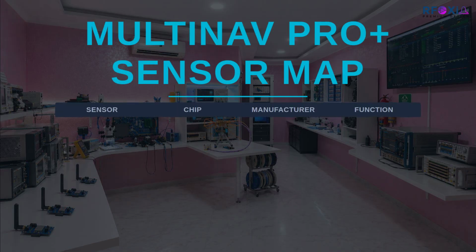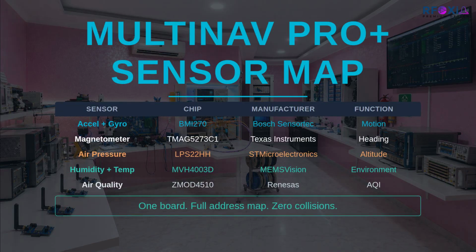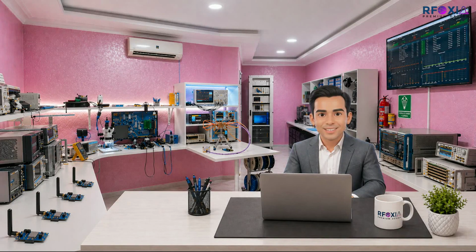These are not arbitrary choices. They are selected partly for their performance and partly because their address spaces do not overlap with each other. There is no conflict to resolve because the conflict was avoided at the selection stage for every sensor. So that is the architecture. One bus, 7 addresses, no collisions, no multiplexers needed. Now let me show you the actual hardware and walk through what is physically on this board.